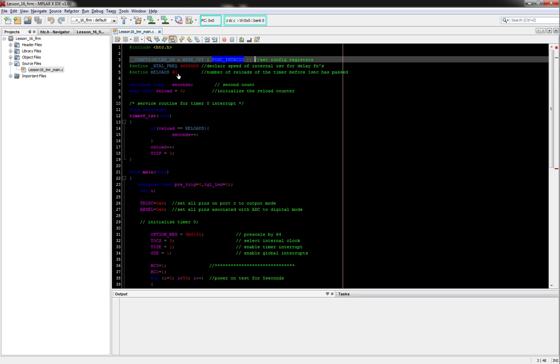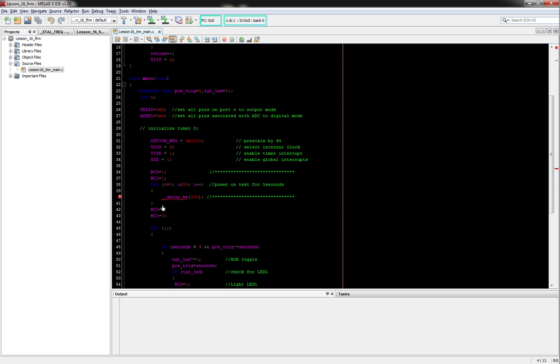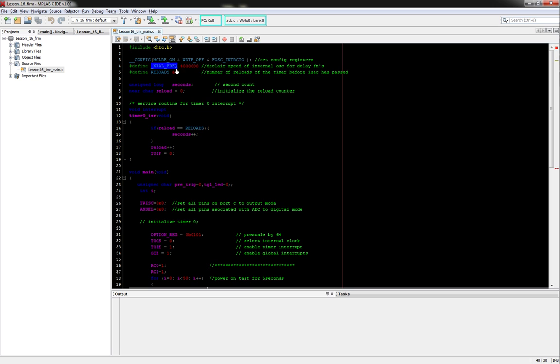That's going to use the internal oscillator, and you are not setting the internal oscillator, you're just defining what oscillator setting you have chosen, so that if you use any delay functions in that function, it knows what frequency you're running. So like I said, if you want to actually change the internal oscillator, you have to change it in a register, and I can't remember the name of that register right off the top of my head. You have to look in that one section of the data sheet, and then you'll be able to find what register it is to program.